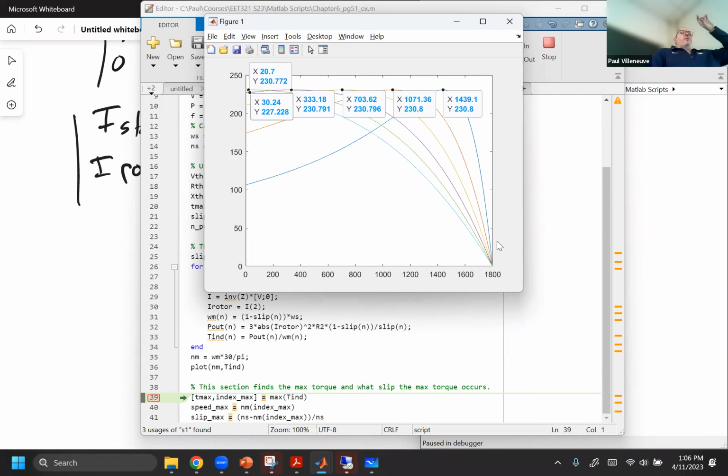There's a waveform that causes a magnetic field that rotates faster than the mechanical speed. There's an AC frequency that's induced on the rotor circuit, and its frequency is such that that rotating magnetic field plus the actual shaft that it's rotating on add up so that the magnetic field spins at synchronous speed.